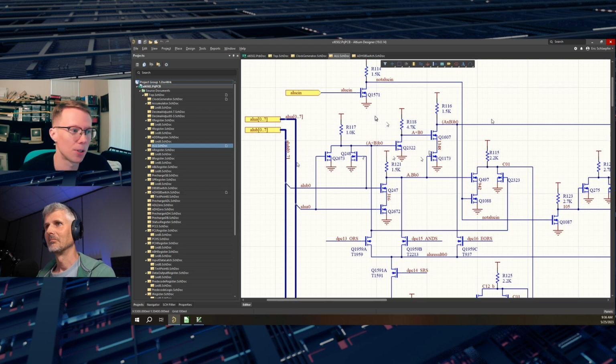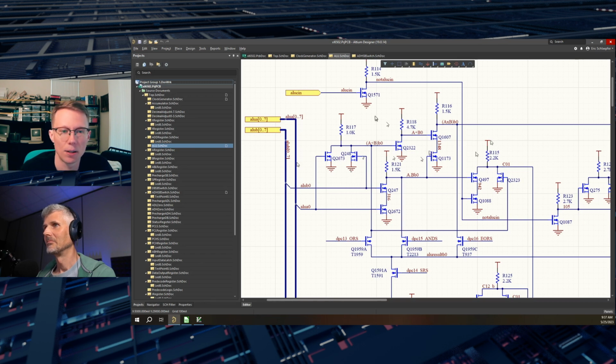So for example, you might see an AND-OR gate. It could be like two AND gates stuck together with an OR gate, and they're all drawn as a single symbol, all stuck together with no wires in between. And that would represent a structure like this right here, which is just made up of 3 transistors. So there's some interesting composite logic gates that you can make. Occasionally, they'll draw a single transistor if it's an open collector, I should say open drain, type of circuit, or if it's a transmission gate. But typically, they would draw that as a gate.